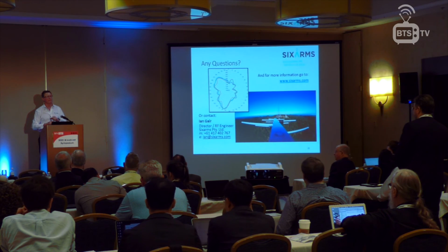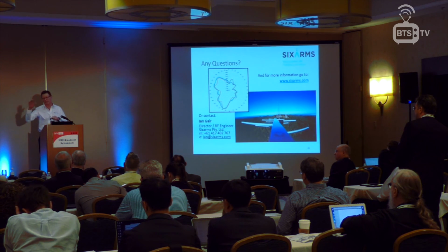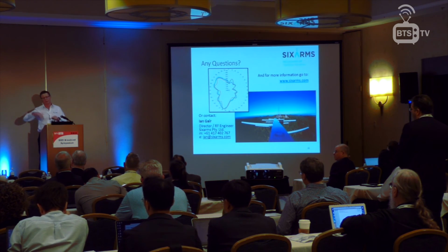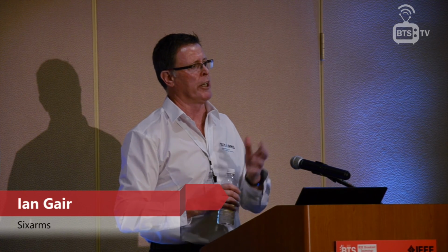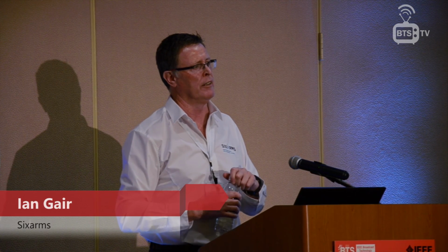We've done it over seawater. Close to the seawater level, you get some. As soon as you get up where the midpoint reflection is back on land, then it's fine. Yeah, and you were generally measuring high gain antennas, so it's maybe less of a problem. Yeah, it's the lower gain you're going to have the problem with, with the wider beam. That's it. So when you get close to the ground, you get poor rejection or discrimination from your receiving antenna. Yeah. Okay, thank you.